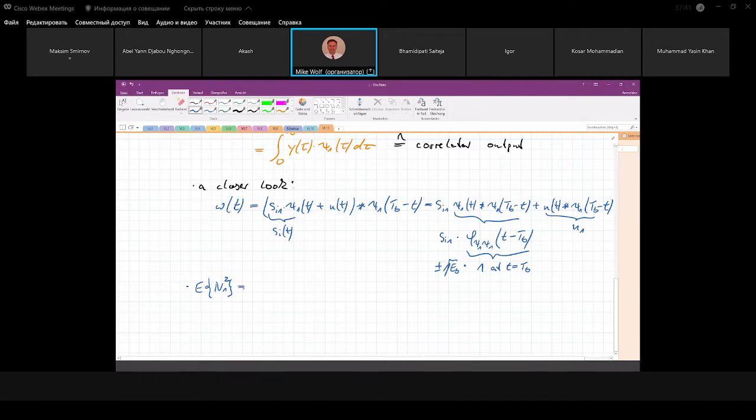So we have additive white Gaussian noise, okay? Additive white Gaussian noise with a power spectral density N0 by 2. This is the input noise power spectral density. Then we have a filter transfer function, which is G of f. But the noise power spectral density at the output of this filter is N0 by 2 times the magnitude of G of f squared.